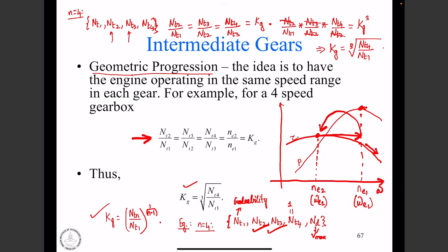If the engine RPM increases and the speed doesn't increase, that means there is a lot of slip. That's all I can interpret, but maybe I didn't understand the question completely. When we are past the peak point and torque starts to decrease, if we are giving throttle and engine speed is also increasing, then sometimes there is no increase in the vehicle velocity.